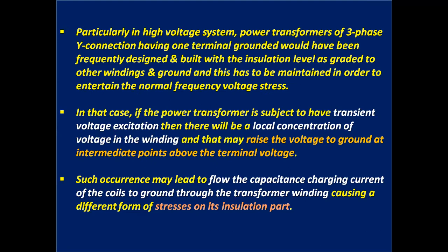In that case, if the power transformer is subject to transient voltage excitation, then there will be a local concentration of voltage in the winding, and that may raise the voltage to ground at intermediate points above the terminal voltage.